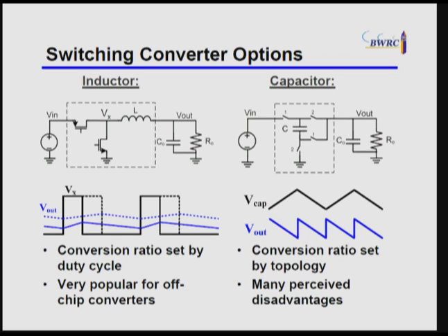In case you haven't seen them before, the basic idea is that these two switches here, you can almost think of just like an inverter. But what you're really doing is changing what percentage of the time that inverter is outputting the input supply, and what percentage it's outputting ground. You're creating this square wave kind of waveform, which goes through this LC filter to get the DC value at the output. What's nice about this is that it's pretty easy to change that DC value by just changing the duty cycle of that inverter at the input, okay?